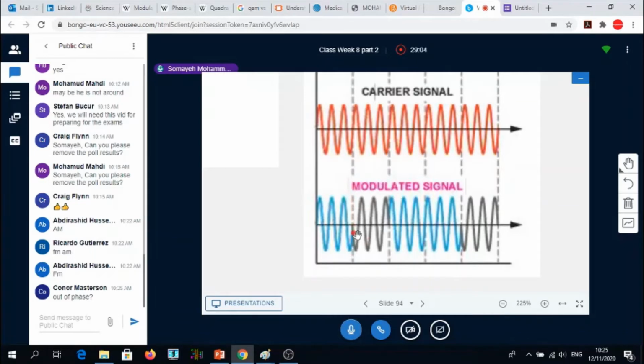At this point, you see that the phase is affected, and the sinusoid is not continuing its path. Let me use my annotation tool. If it wanted to continue its usual path, it should have gone upward at this point and then come back and go back this way. But because of the drop in binary, it is inverted. Can you see the inversion here?